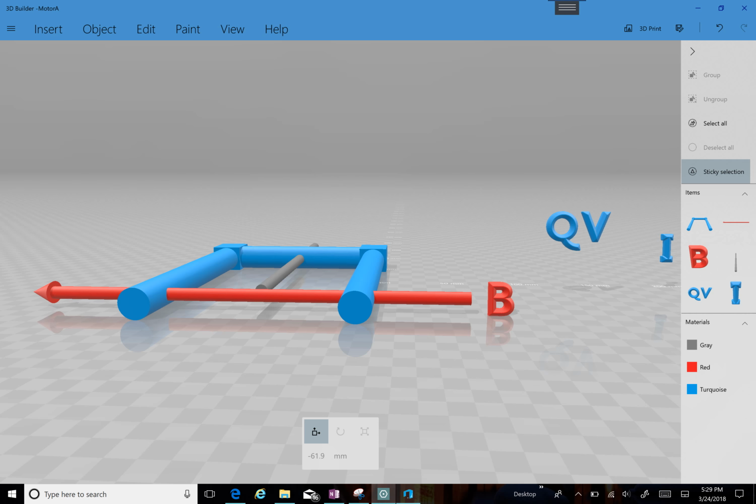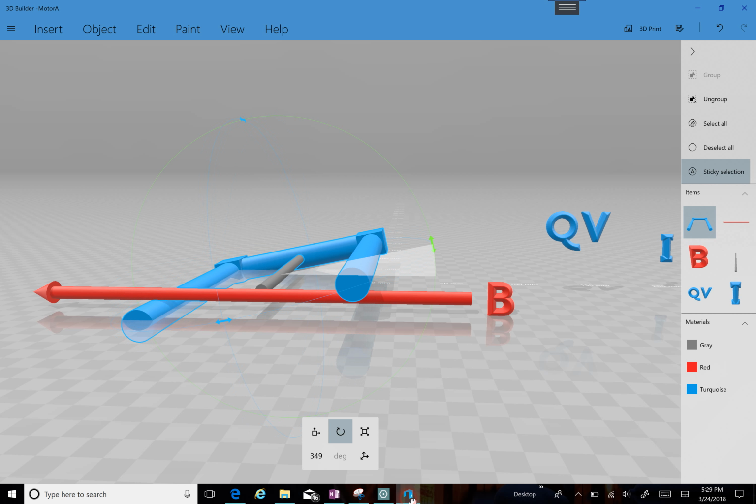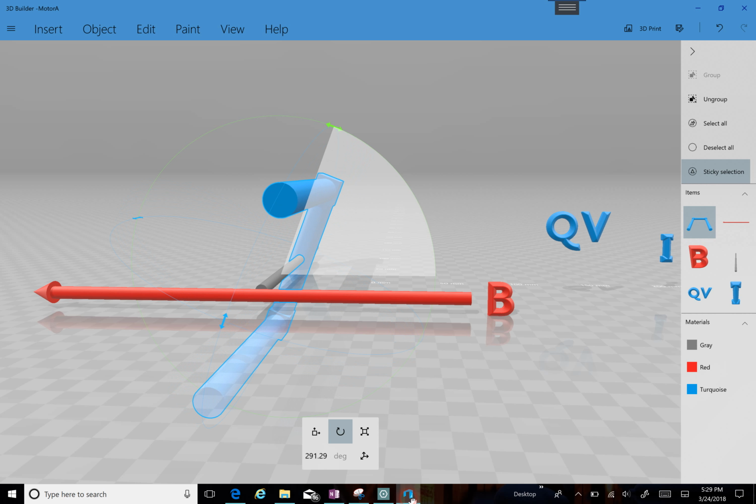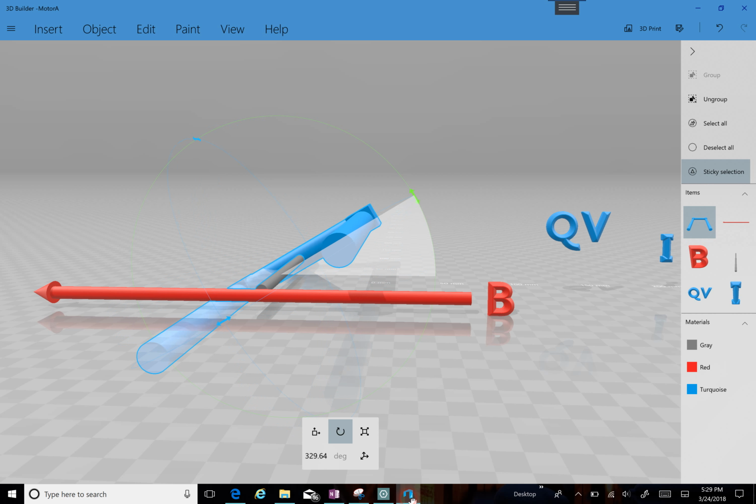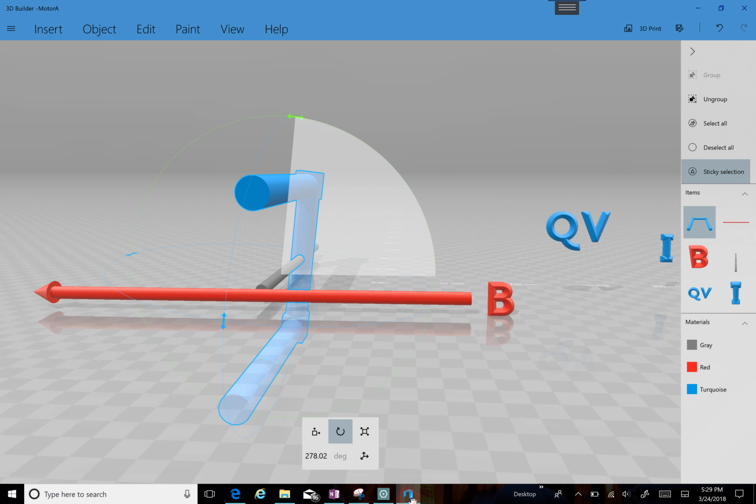And if that's the case, let's go back to our dynamic drawing. If the right-hand one is being forced up and the left-hand one is being forced down, hopefully you can see, and the thing is free to spin on the axle, this wire loop is going to spin. We've created a motor. We put current in on the wires, and the fact that there's a magnetic field oriented in the way that we show here means that the wire loops develop forces like we just figured out with the right-hand rule, and the wire loop is going to spin on the axle.